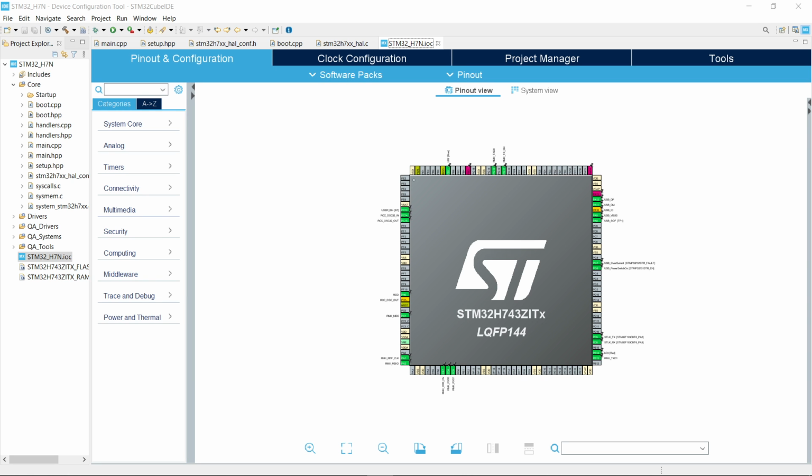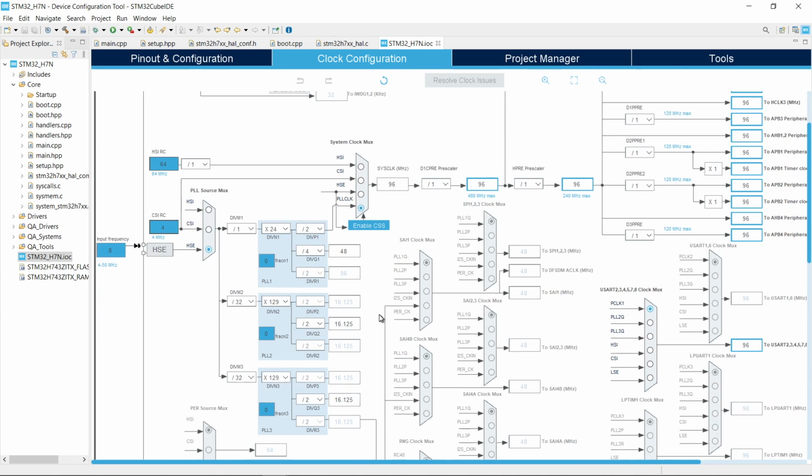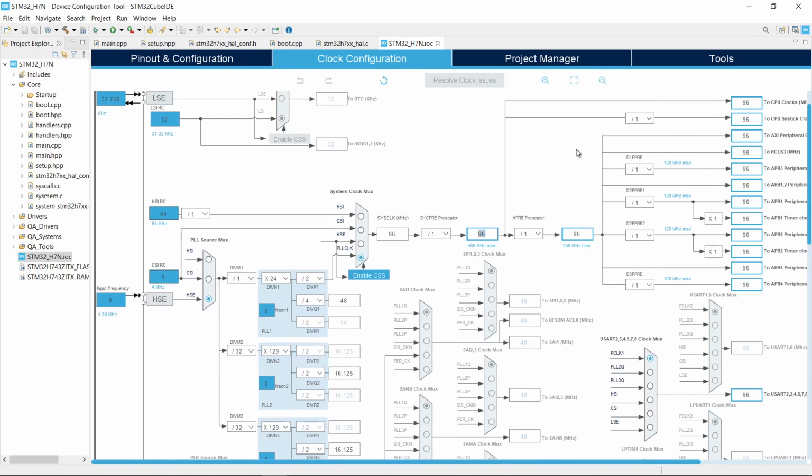Okay, we jump into our clock configuration, and it's the easiest way to get a bit of an idea of the particular values that we're going to need in here for our M, N, P, Q, and R values for our PLL. And also, if you're trying to figure this out for the other PLLs and figure out various pre-scalers as well, you can just go through and actually pop in the particular value that you want into one of the boxes and then get it to actually calculate.